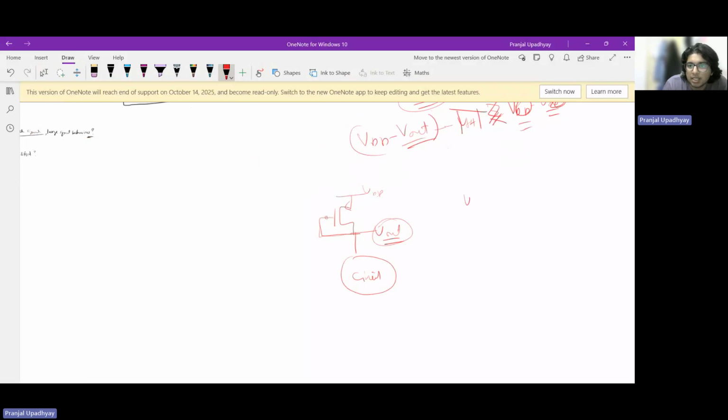So that limit is set by this equation that we already know for PMOS, that this overdrive must be greater than 0. And so we can just set the upper limit for our Vout. So this is basically the swing limit that we have for PMOS load on output, and this is the upper limit of output.